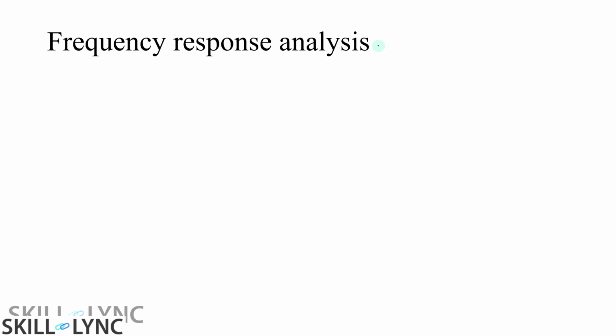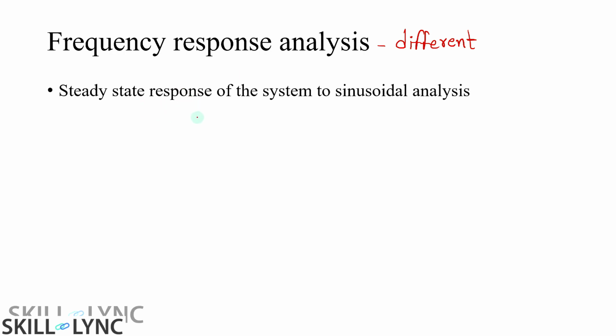This response analysis is based on different frequencies over the period of time. So we apply different frequencies to the input and analyze what is happening in the output, and that is called a frequency response analysis in simple words. Or in other words, we can say that the steady state responses of the system when it is subjected to the sinusoidal inputs.